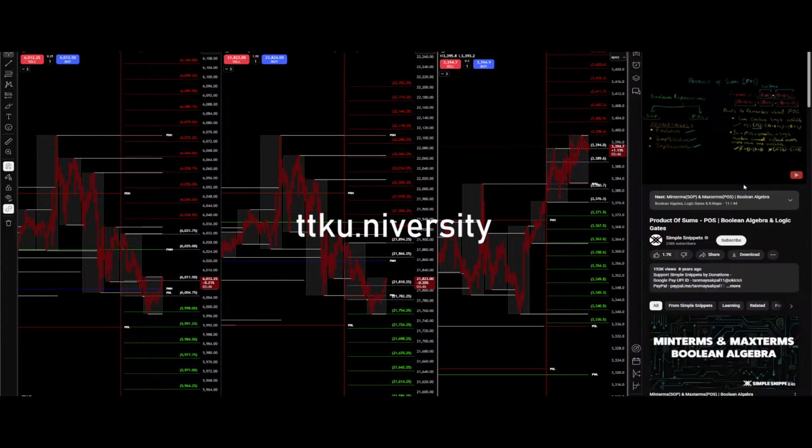In a POS expression, a single overbar cannot extend over more than one variable. That is, check out this example. Here we take the complement of these two variables together. So this is not allowed. Again we take the complement of these two variables together. So this is again not allowed. But take a look at this example. Here we take the complement of a single variable. So this is a valid POS form.